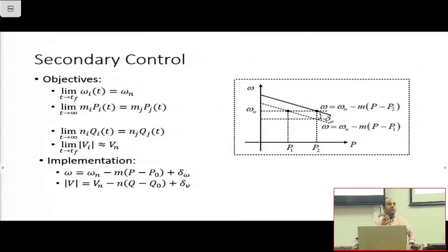But you know, in a system you always want a regulated frequency, for example 50 Hz. Now here we are intentionally decreasing the frequency, so we have to increase the frequency now. Now the question may come, if you have to increase the frequency, why in the first place did we decrease it? The decreasing was necessary to ensure that we share the power equally. We had no choice, we had to do it. Once we have done it, what can we do to restore the frequency?